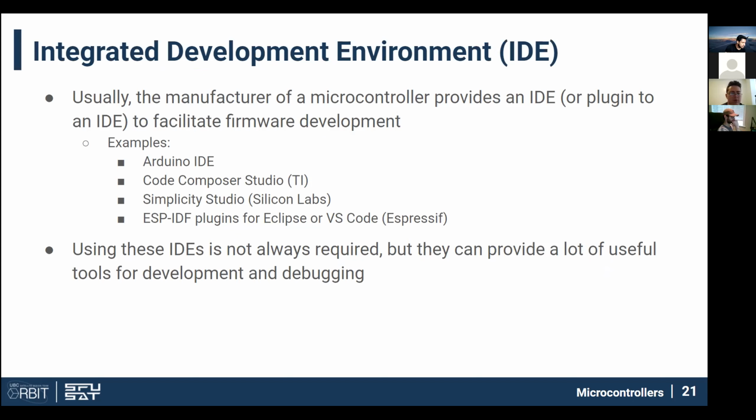Watchdogs are memory mapped too. Watchdogs can be included in the microcontroller, in which case they would be a memory mapped peripheral, or they might be included in a way that's more obscure. For the TMS 570, we actually have an external watchdog. It's a device outside the microcontroller, and we use a GPIO pin to pet the watchdog. In that case, it's not memory mapped because it's outside of the microcontroller.